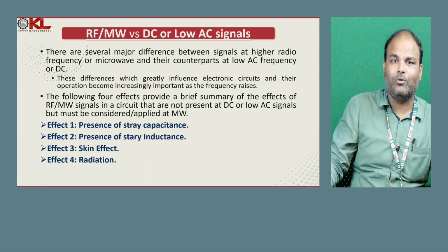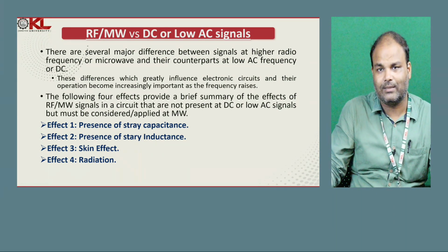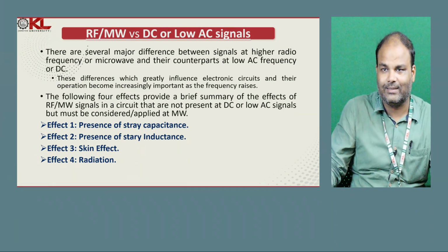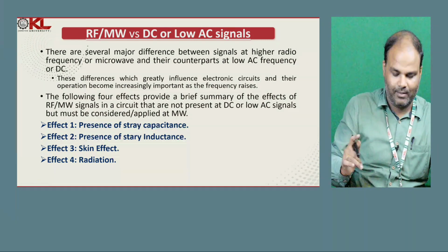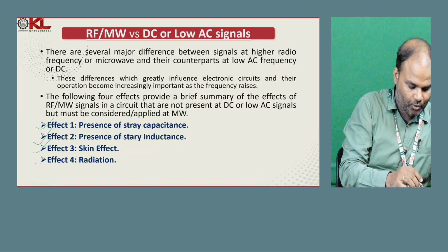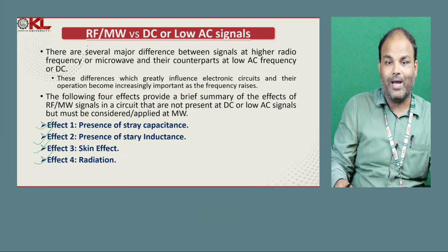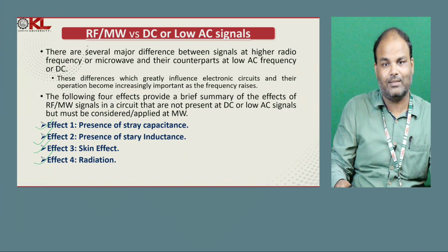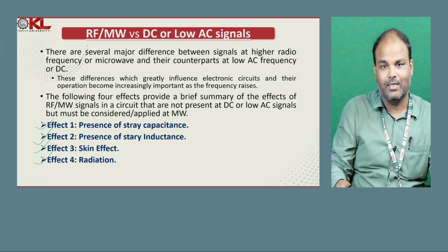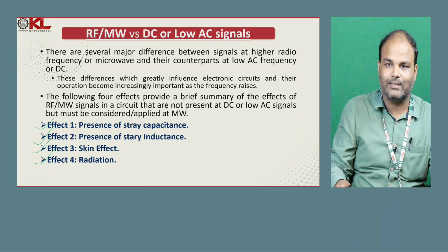If you are thinking about RF and microwave circuits, instead of DC or low AC signals, then we will feel four effects. So these four effects come into existence: presence of stray capacitance, presence of stray inductance, skin effect and radiation.